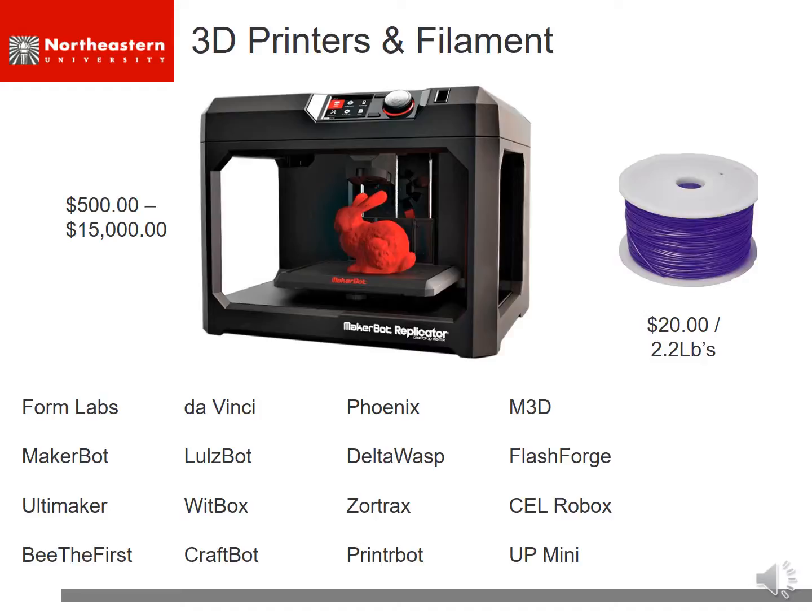A consideration when you're doing prototyping is the density of the material. People ask me often, how much does it cost to do a 3D printout? Well, it's a function of the size of it and the density of it. If it's solid plastic, it's going to take a long time to print it. It's going to use a lot of material, and you're going to need a special printer to do it. So what you try to do is optimize your design to use as little material as you can and keep the size relatively small. Just a lot of considerations.